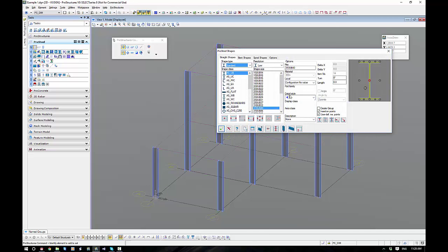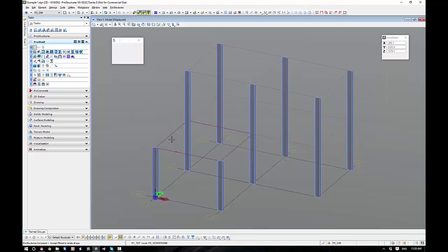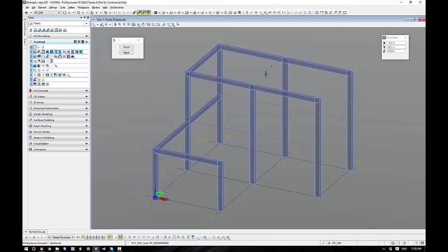Okay, we'll put our horizontal in. Remember, if we want it horizontal, I'm going to go 310, the same size, must be top of steel, and I'm just going to do it quickly now. So let's pop in our beams. Simple as that. So I select, accept, because I don't need to rotate. So it's just left click, left click.